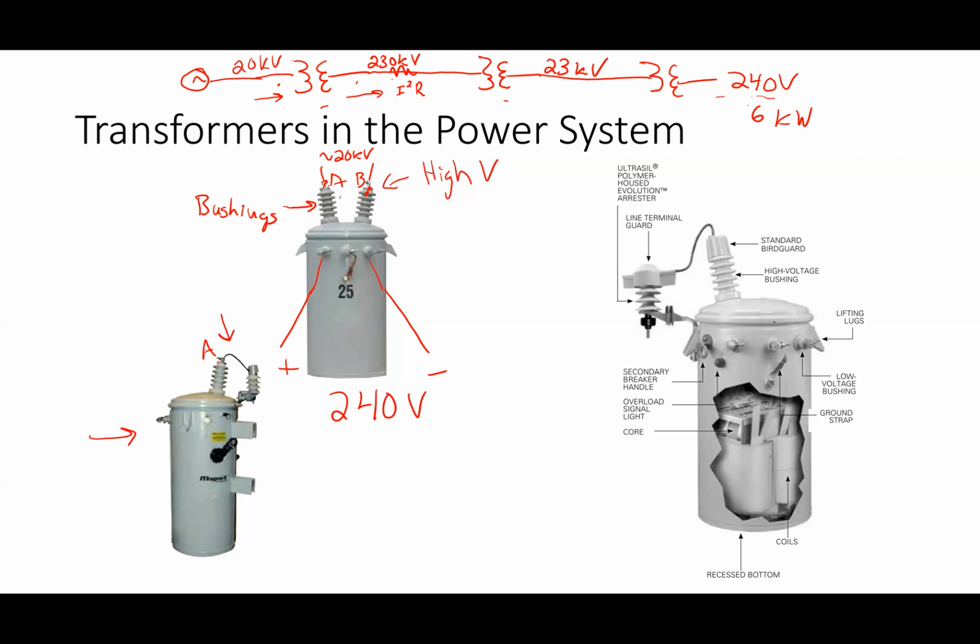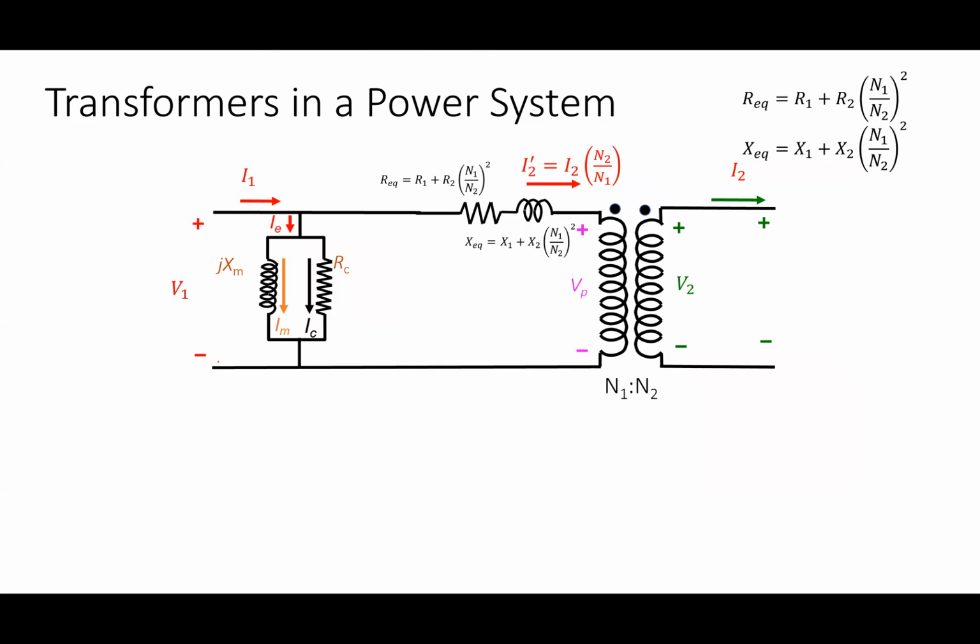So anyway, the most important thing usually is what are the voltage ratings, and then what's the power rating on the transformer. All right. So like I said, if I'm operating this guy at rated current, usually we say that this here doesn't really matter. Right? At rated current, the magnitude of I1 is much, much greater than the magnitude of IE. And so the picture we make is this one. Okay. All right. So this is the picture that we get for this particular transformer.